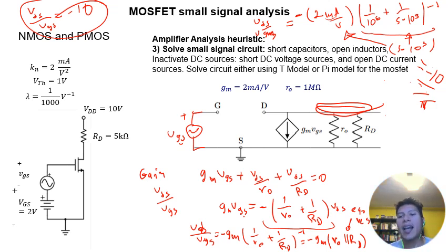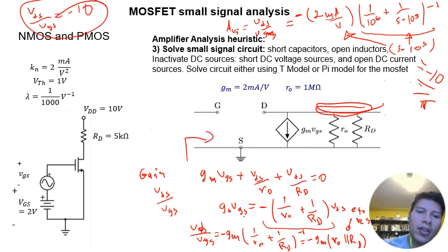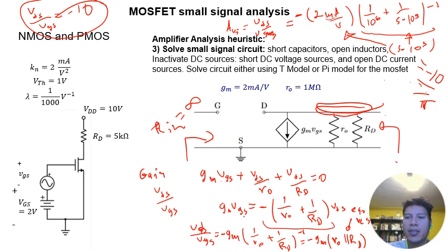And this is actually how we're going to analyze circuits. So now we know what the gain is. This is what we're going to call the open circuit gain, or AVO, for our circuit. To determine the Thevenin resistance, we would look at the input resistance looking into the input terminal, which in this case is VGS. In this case, it's an open circuit, so Rin equals infinite. And our Rout would be the resistance looking into this output terminal.